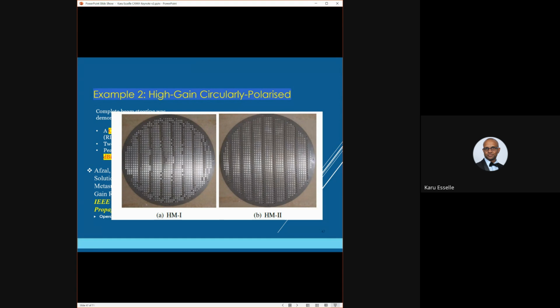When the wave propagates through the dielectric slab, when you add metal patches, it increases the phase shift through the slab due to the effect of the patches. And when you drill holes, the effective dielectric constant of these unit cells decreases, so the phase shift decreases. So that is like effectively getting negative phase shift relative to the substrate.